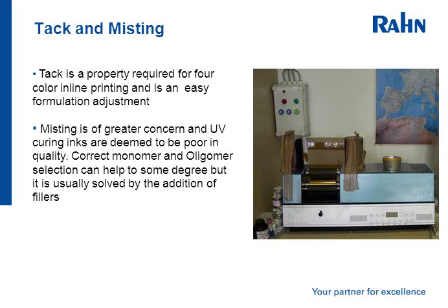Tack and misting, as mentioned at the beginning, are 2 properties that are looked at in great detail for lithographic inks. Tack is the property of the stickiness of an ink, and is required for the inline printing of the 4-color process, where the printed ink must be followed by the second ink, which must not remove the first ink, and as you go through the process, each ink is accepted and continues to form the finished print.